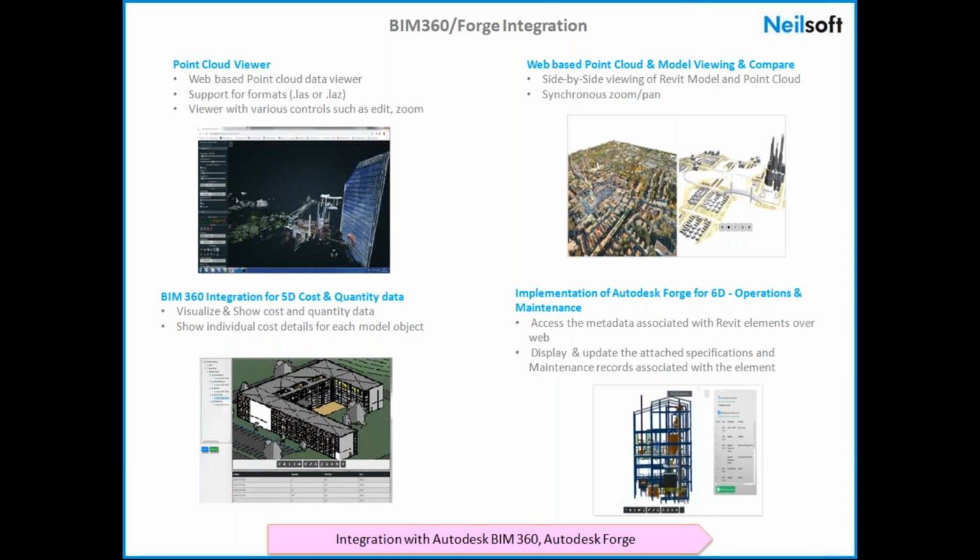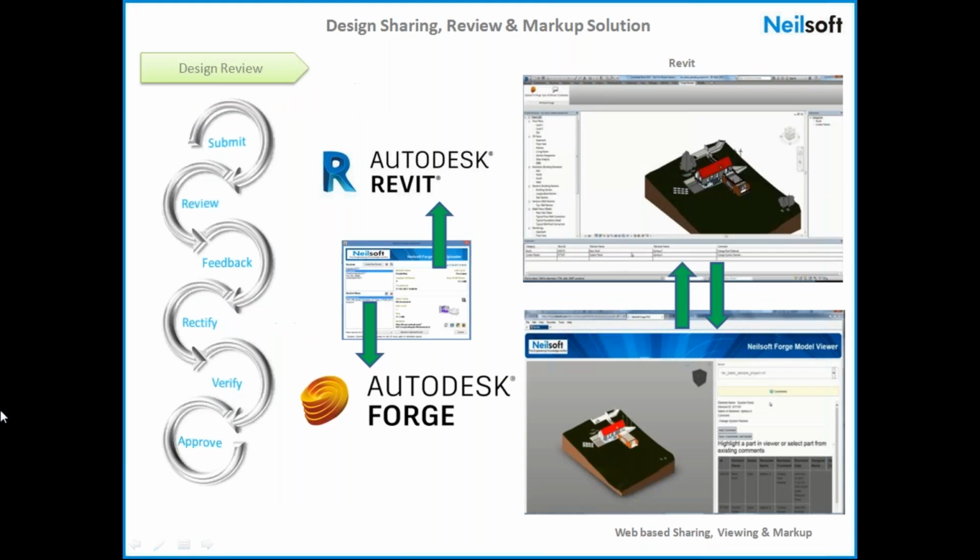Or moving on to 6D, which is operations and maintenance, where we implement Forge along with the metadata, which is your specifications, your maintenance cycle, your maintenance records, so that the owners and operators can easily track what maintenance activities are to be performed, what are the previous maintenance records for various equipment, what was done, the cost associated with it, who are the vendors, and so on. So these are some of the examples of the integrations that we have developed.